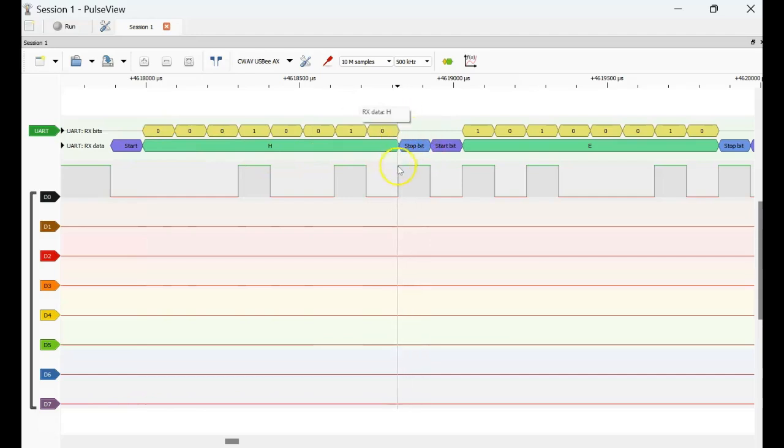And the frame between this point and this point is the data, which is the binary of the ASCII uppercase H. Now, if you look at this 1, this is the output from PE5, and another 1 here, and these are all zeros, so this is all space here, 2 zeros, space, and this last 0 is a space, framed between the start bit and the stop bit.